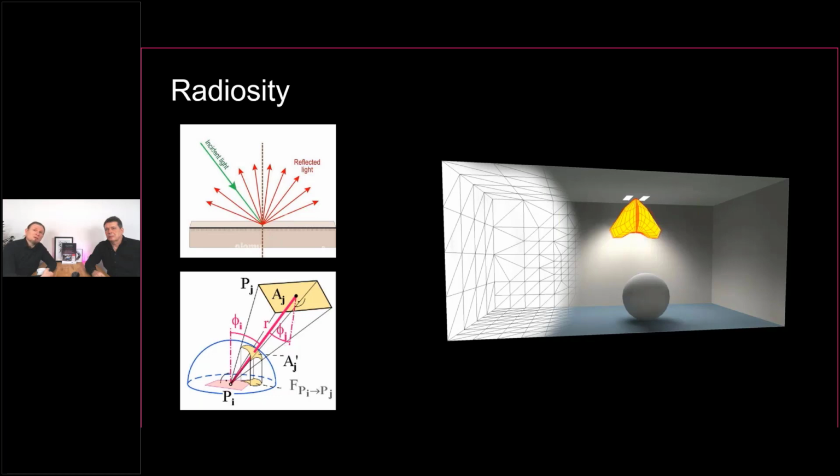And this method, as Lars said, has no specular or non-diffuse reflectance like a mirror, and also no transmission. So no glass, no effects from passing light through material. It's just about surfaces which are perfectly diffusing. But the color counts, so the reflection degree, so it reflects the light, and this is the issue in radiosity, or in light calculation at all: the indirect part.